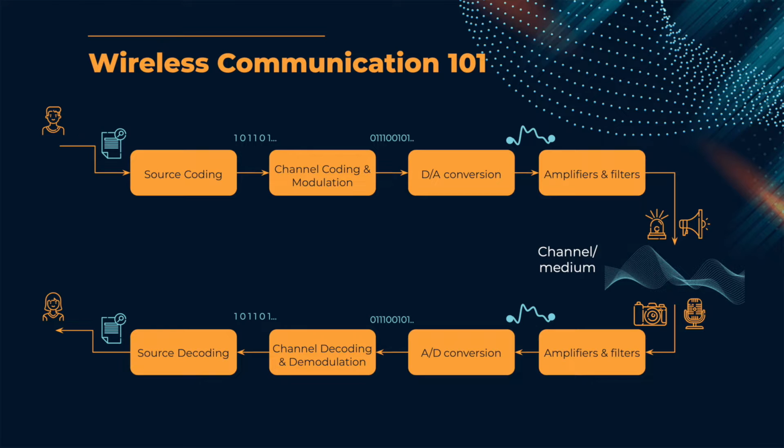If you look at the basic building blocks of a wireless communication system, in any digital communication textbook, you will see some variation of this. You have some information that you want to transfer from one point to another. You take that information and convert it into some kind of representation that you can transmit. In digital communication, you translate it to a series of bits and bytes, ones and zeros. Then you do channel coding and modulation. You have these bits and bytes, but you need to represent them using some physical phenomenon which we can transmit, like sound, light or electromagnetics. Then you convert that to the actual physical phenomenon. If you're transmitting with sound, you use a transducer or a speaker, or if it's an optical system, you use an LED. On the other side, you use a receiver: in the case of sound, a mic or something similar, and underwater, a hydrophone. You do the reverse on that side, and you retrieve the data.